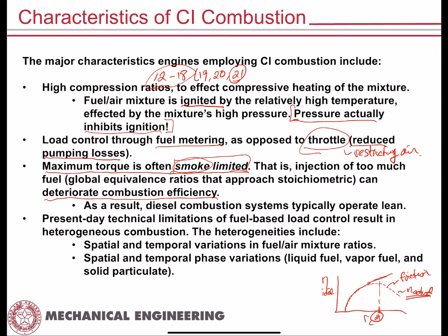So as a result of that, diesel engines, of course, typically operate lean, right? You know about this. We've talked about this all throughout the semester, right? And so now when you take a look at this, you say, okay, compression ignition engines operate with higher compression ratios. That has a tendency to raise efficiency so long as you're within a reasonable range of compression ratio. I take this nasty entropy generator, the throttle, and I send it to the museum, and control my load through fuel metering.